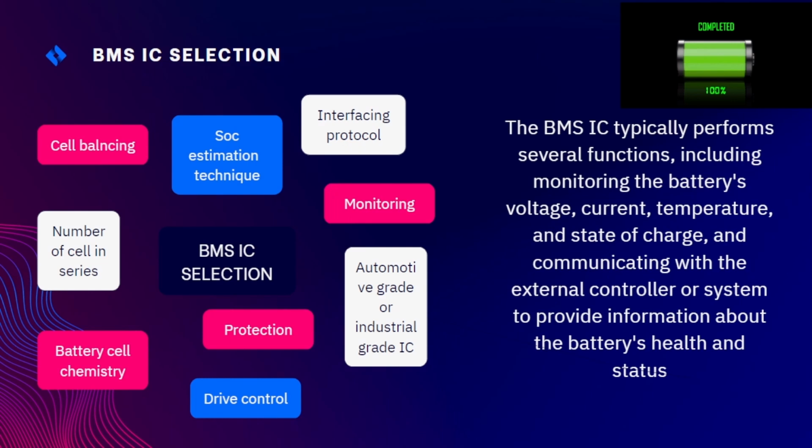Many of the ICs have voltage monitoring and temperature monitoring built into the IC. So current monitoring would be more difficult to find in an IC. In the case the BMS chip does not have the monitoring for current, you would need some external circuitry to provide the monitoring.